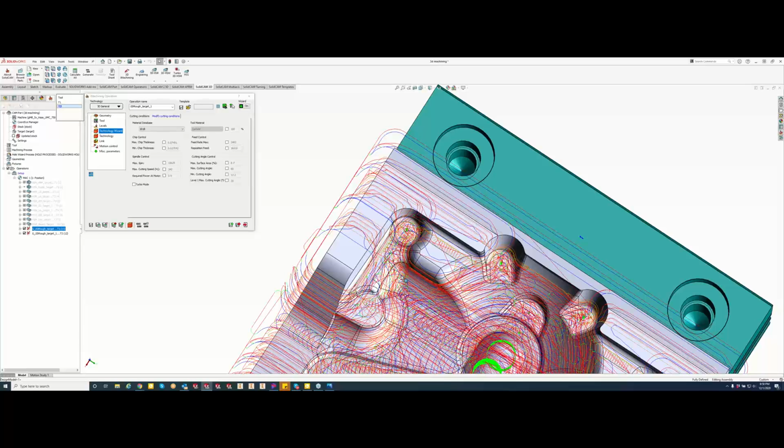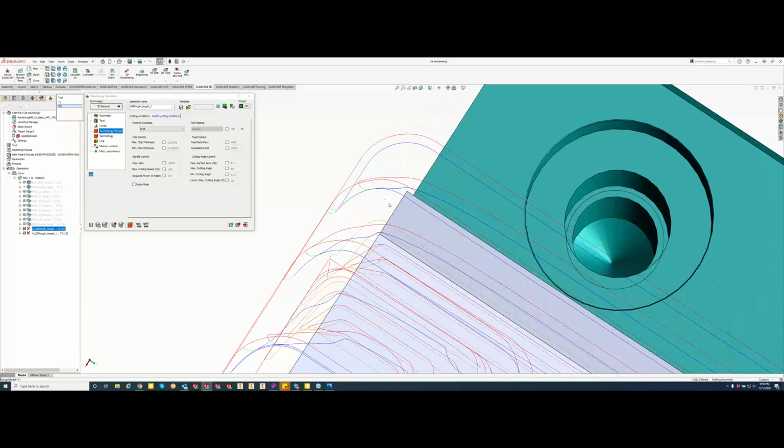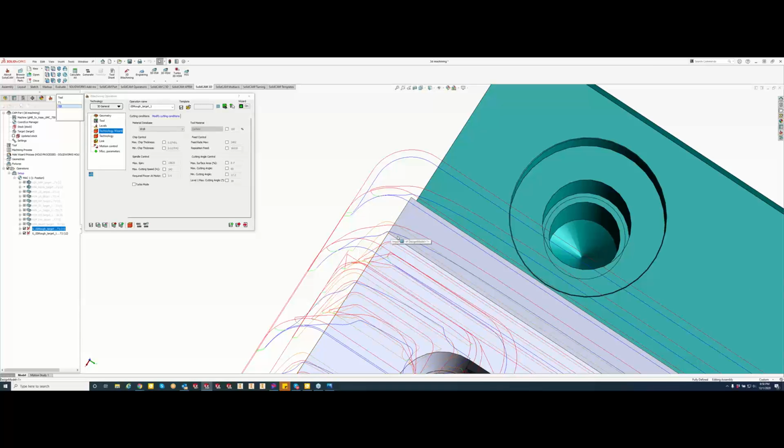Oh yeah, definitely, Kevin. And that's the whole thing, like that acceleration and deceleration time that has to happen between, like you said, a G0 move or a G1 move. Why keep flip-flopping back and forth and causing undue stress on the machine? So keep it in that G1 move and then just accelerate and decelerate the feed rate. Makes perfect sense. Yep. And when you guys are looking at the path right here, if we take a corner, you won't see any 90-degree corners in here. They're all nice radius corners, so we're not getting that machine jerk going from Y positive to X positive. Yeah, exactly. No sudden stops and starts.